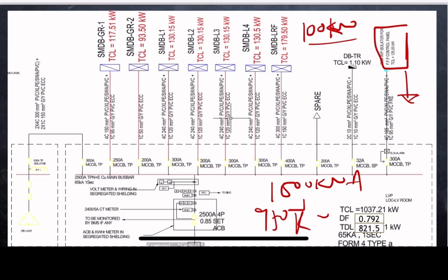Here, when the fire pump starts, when there is a fire in the building and all the HVAC loads are integrated with the fire alarm, the HVAC loads get shut down. The fresh air loads, AC loads, all will get shut down, because all the AHU and FAHU are directly interfaced with the fire alarm.